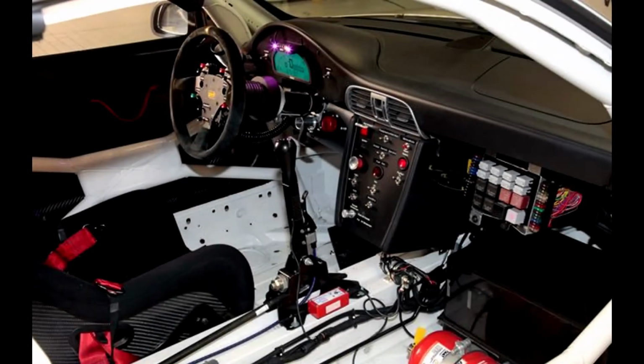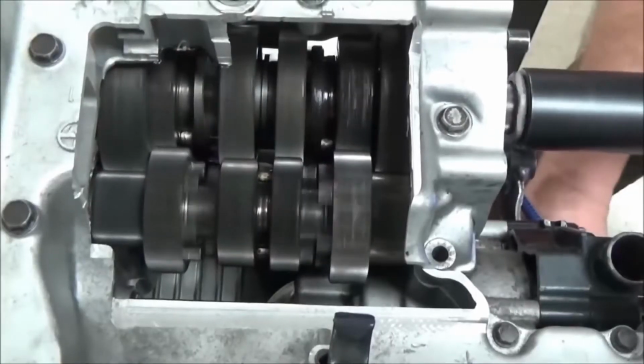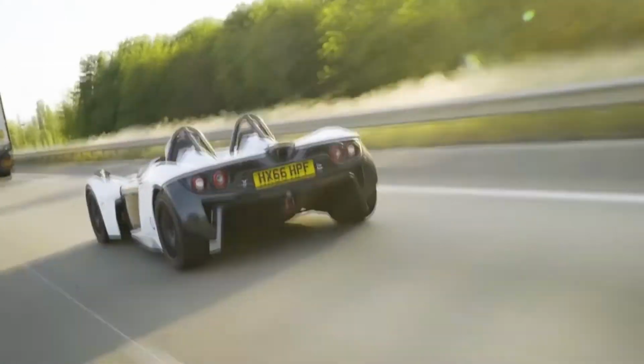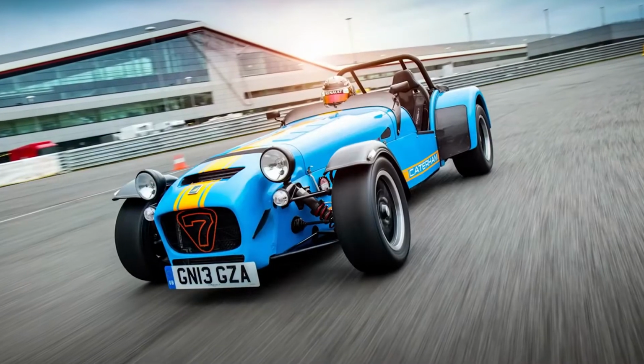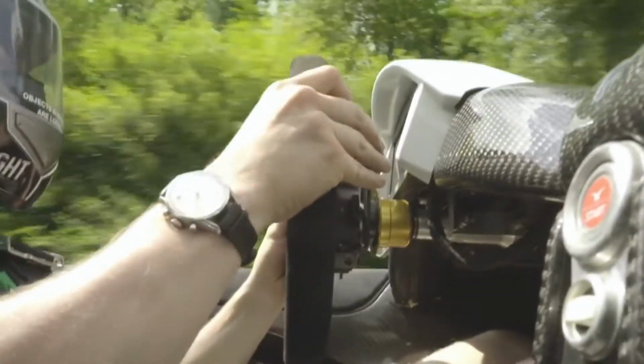Automated manual transmission. An automated manual is similar to manual because it has a mechanical clutch, but the clutch isn't controlled by the driver with a clutch pedal. It's actually automated using electronic, pneumatic, or hydraulic controls. It's referred to as direct shift gearbox, DSG, or a sequential manual gearbox, SMG.